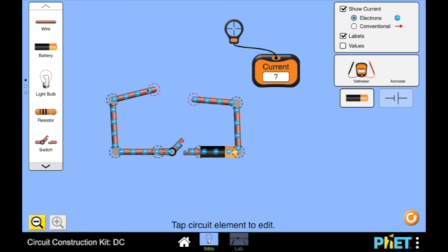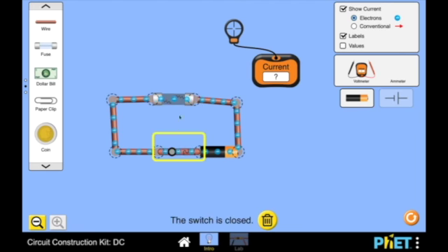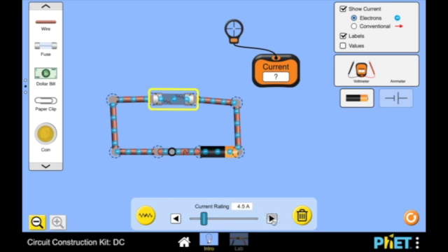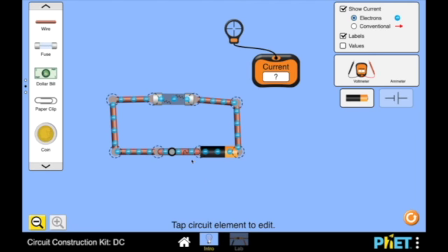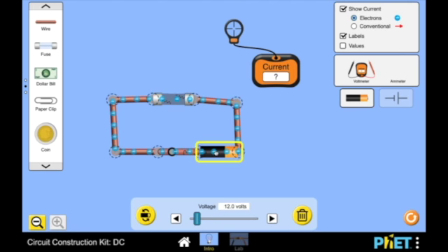There are some other items that we could put inside of this circuit. If you click the down arrow, you will see there's a fuse. And if we insert our fuse and then hook this up to our circuit, clicking on our fuse, we'll see it's rated right now at 4 amps. So when I close the circuit, sure enough, the fuse breaks. So if we click the fuse again and give it a higher rating, now for 5 amps, now we should be able to, well, I'm going to have to reset this. There we go. It's still breaking, and part of this is because we have no other resistance in our circuit.